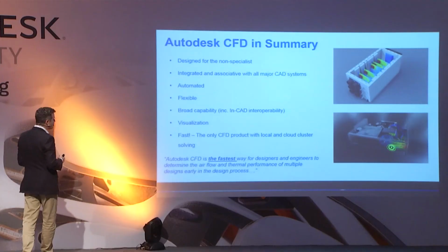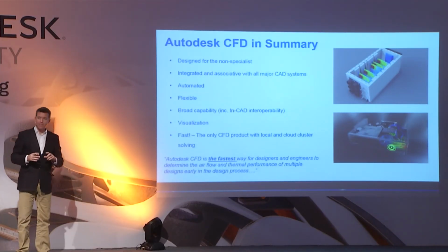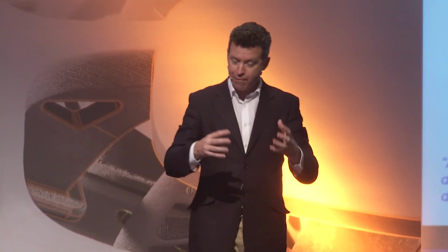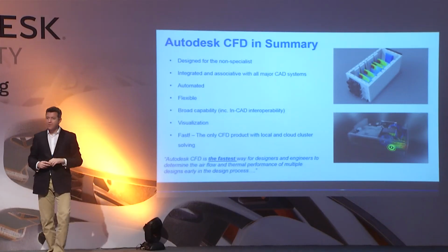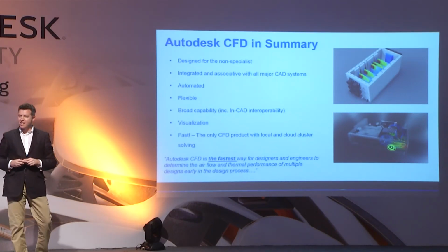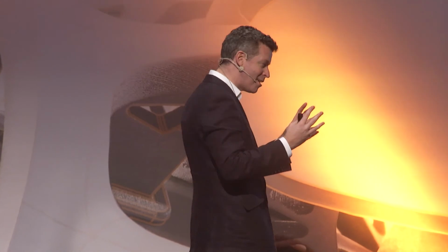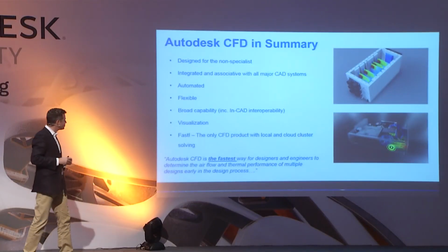Now, there's a broad range of capabilities. I've not gone into all of them, but it's possible to connect the CFD solution with Nastran In-CAD. And Nastran In-CAD is a product that's now available as part of the Product Design and Manufacturing Collection. It's now free within that collection. What that will enable you to do is look at the temperature results of the analysis and import that into Nastran In-CAD. Nastran In-CAD will see that and then calculate for you how the product deforms or how the stress is increased based on those temperature variations. So it's a kind of closed loop solution.